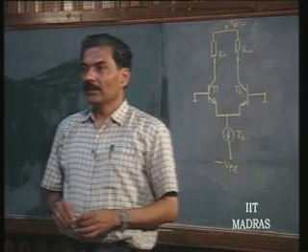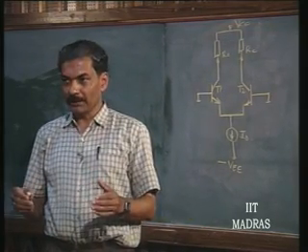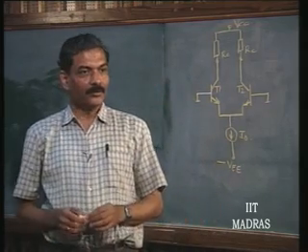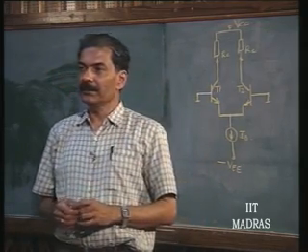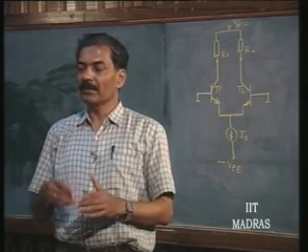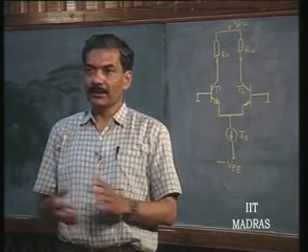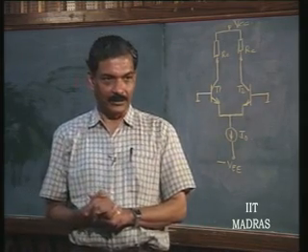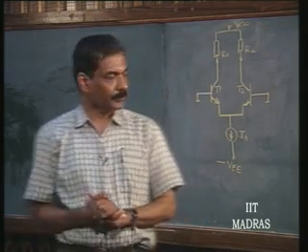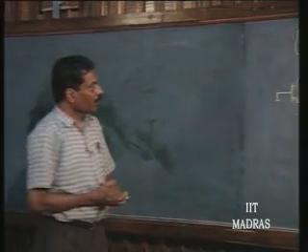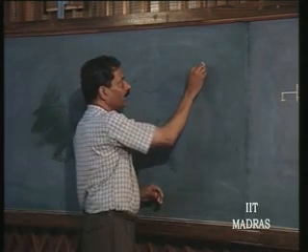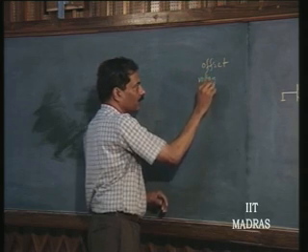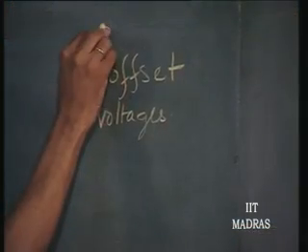So far we were discussing small signal properties as well as large signal properties of the basic differential amplifier. Now, we will go to the secondary properties of the differential amplifier, which also become important when we use this in particularly low frequency or DC amplifier stages, the so called video amplifier stages also. Let us see what these are. What we are now going to discuss will be primarily to do with offset voltages, output offset voltages.